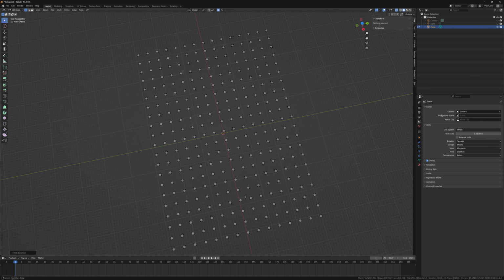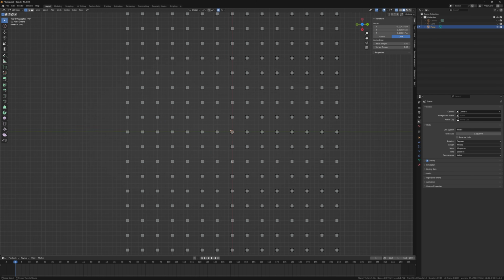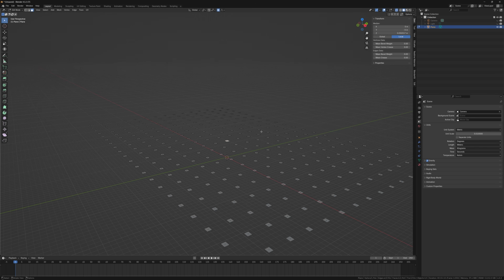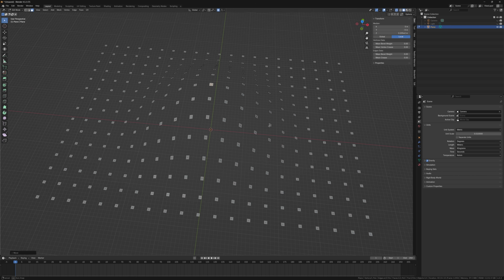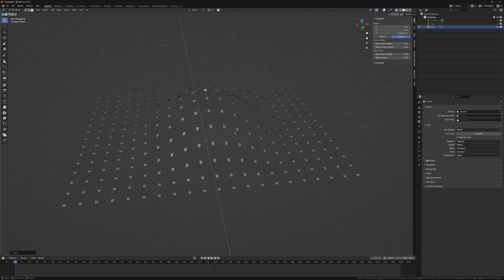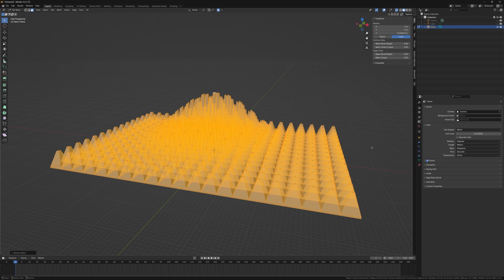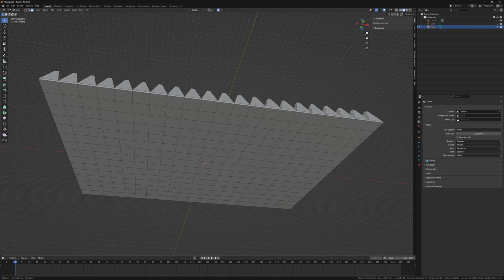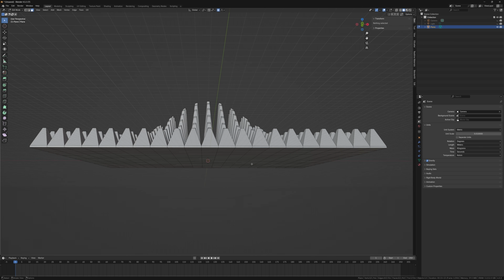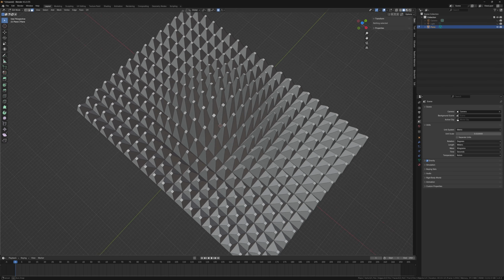So now we only have our top vertices visible. So we're going to select the center again. Or you can switch to faces, only the center face. And if we now do G and Z with the proportional editing, you can see it only lifts those surfaces. And if we switch back with Alt H to make everything visible again, you can see that the bottom is still where we started. So with hiding selected layers or faces, you can avoid them being manipulated with the proportional editing.